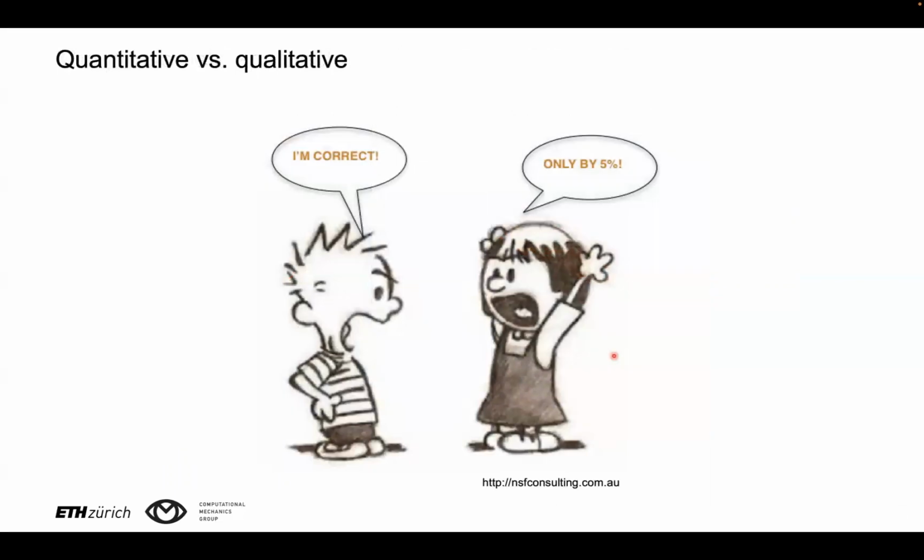Now, one of the first issues that people looked at when the phase field approach started to become popular in the engineering community was the issue of validation. Validation in the early days was performed in a qualitative way, meaning people would look at the crack patterns and be happy when the pattern was reproduced satisfactorily. But quantitative validation means that the corresponding forces or force displacement curves also need to be reproduced accurately, and ideally even local, full field measurements should be reproduced accurately.